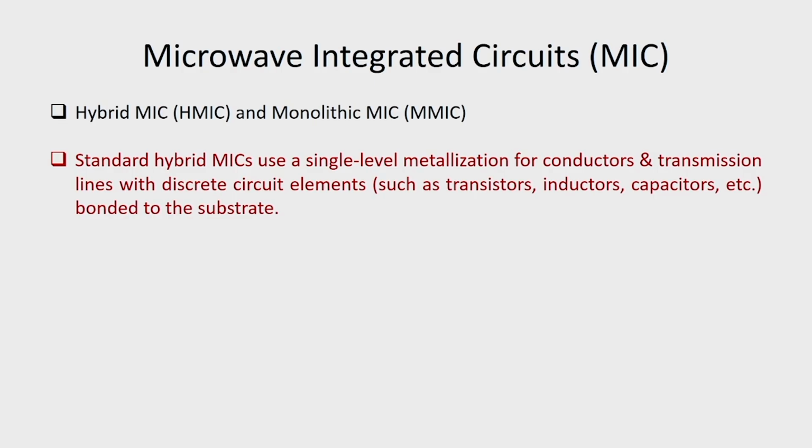Standard hybrid MICs use a single level metallization for conductors and transmission lines with discrete circuit elements such as transistors, inductors, capacitors, etc. bonded to the substrate.